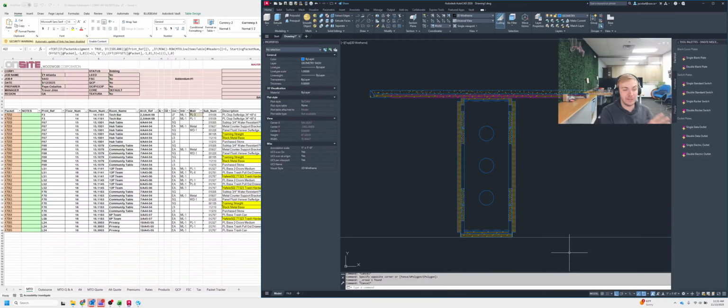So based on the millwork side of the scope, not even considering the other trades like the electrician right now, what we have here is exactly what we would be providing for the client. So this is our stone quartz top, SS1, QZ1 is what we're going to call it. We have our plywood subtop, which we are going to call out as PRBLK later for primed black. We don't want that to be exposed plywood. We want it to look nice and finished. So we're going to prime it black.